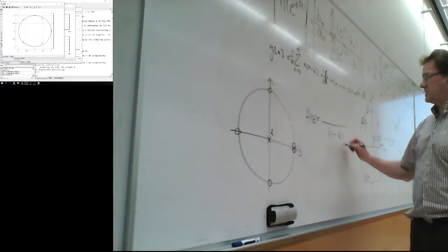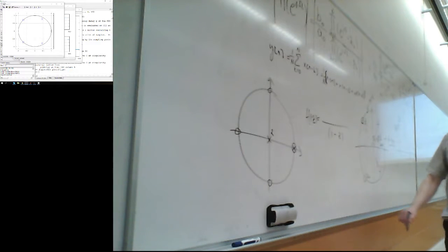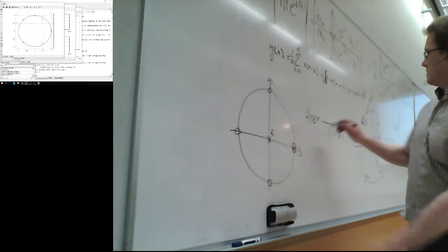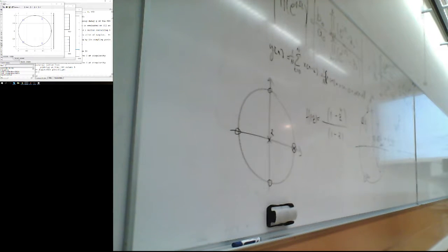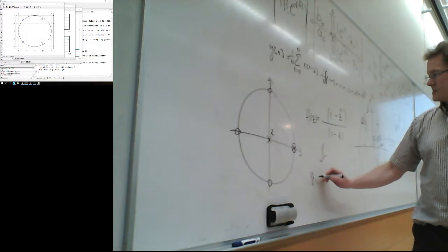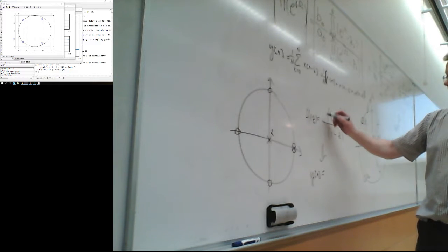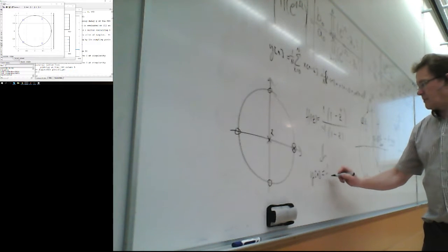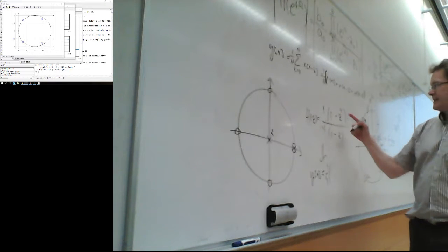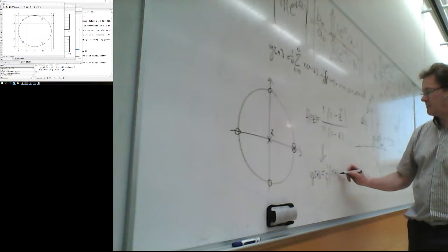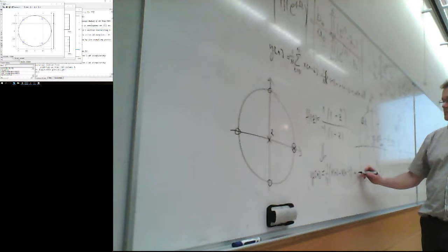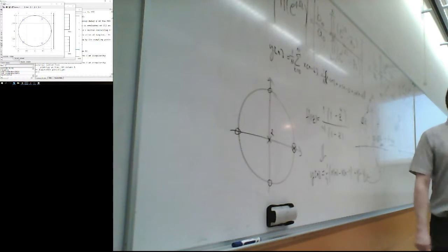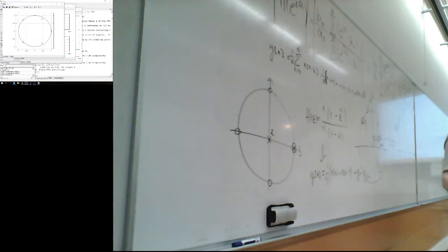You have 1 minus z on the bottom, and then you have 1 minus z to the power 4 on the top, meaning that you actually have the difference equation of, well, that also has the 1 over 4 here: 1 over 4 x of n minus x of n minus 4 plus y of n minus 1. Ta-da! Neat, right?